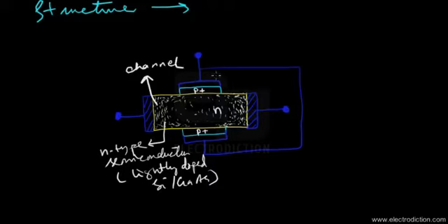Before that, let me mention one more thing. This N-type semiconductor bar, known as the channel, has two other semiconductor P-type regions on its two sides, as you can see from the lines drawn in light blue, denoted by P plus. Now the plus sign, I'll use the white color, that's my mistake there, don't mind. This P plus, with the positive sign, represents that the P region there is heavily doped.